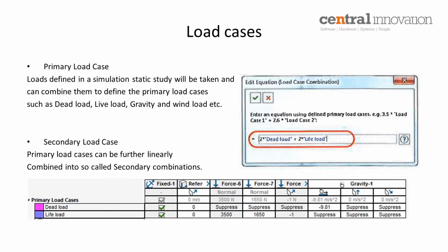You can use a sensor. There is a useful tool inside SolidWorks, sensors. You can create a sensor for displacement, for stress value, for factor of safety value. Add the sensor into the load case manager, so that sensor will track the results for the displacement or stress, whatever value we defined inside the sensor. Okay, so let me move on into the example.